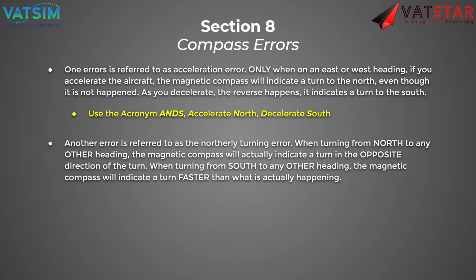That's a basic explanation I can give you. Does that kind of answer your question? Yes. So for 20 degrees, it is unreliable. It's not unreliable. You just have to account for that error. So if you're south and turning to the right, you should overshoot the heading you want to go by 20 degrees because the compass is moving faster.